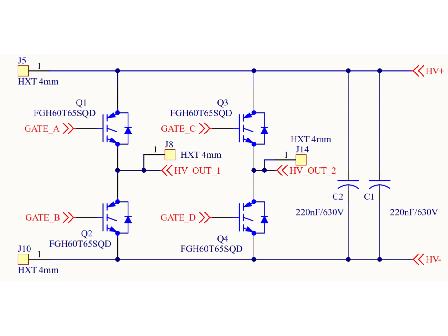With 2 devices conducting at any instant in the H-bridge, the conduction loss per device is only about 5 to 8 watts, resulting in a total bridge conduction loss of roughly 20 to 30 watts. At 20 kHz, switching losses become more significant.